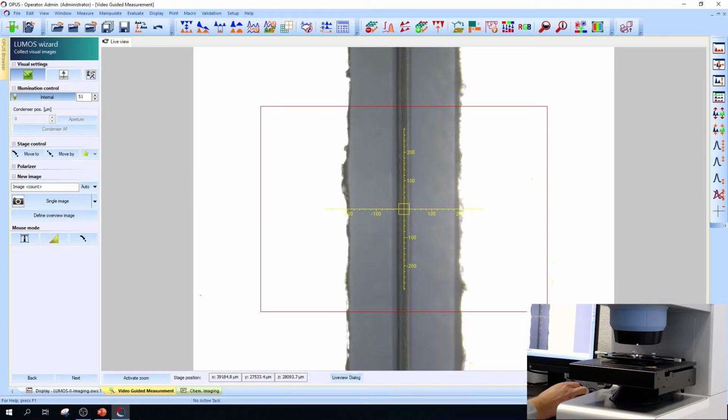So what you can see here is, on the left, the metal brackets from the microVice holder. The same on the right side. You see this bright grayish layer on the left and on the right. This is the PTFE buffer material, and only this foil in the center is our sample itself, our packaging material, which should now be analyzed by FTIR ATR imaging microscopy.